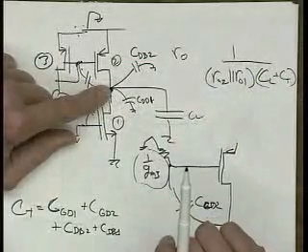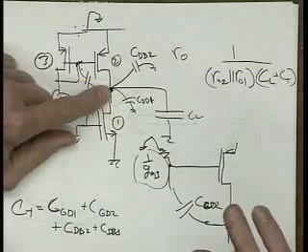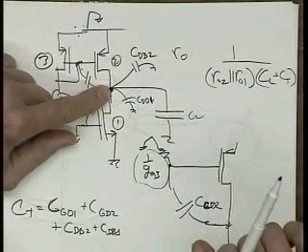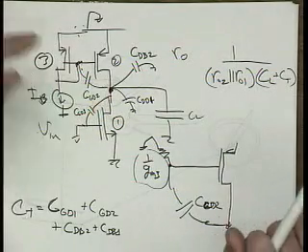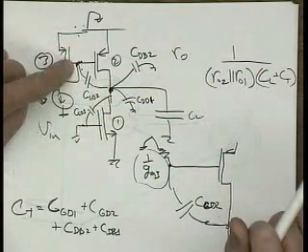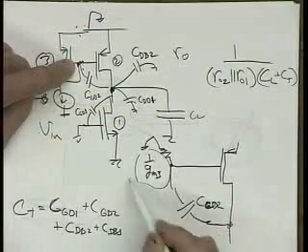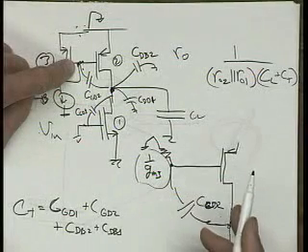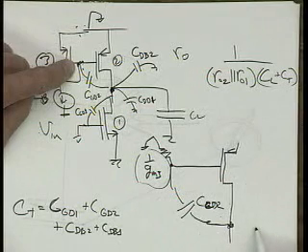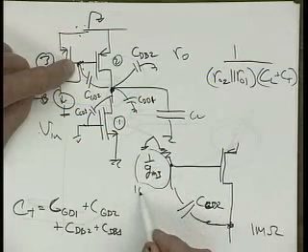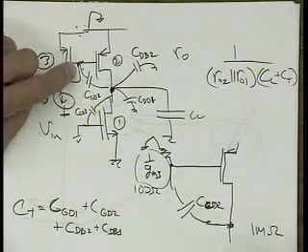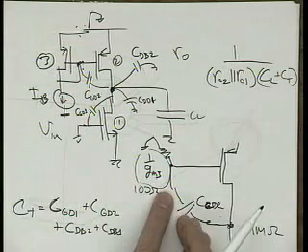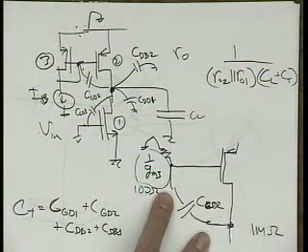Okay, Professor. Yep. Gentleman, question? Okay. So is there CGD2? Do you assume it's a capacitor to ground though? Well, if 1 over GM is small, yeah, you can pretty much assume it's a ground, right? If this node here is megohms, okay, and this is 100 ohms, right? If I figure out the time constant for this capacitor, it's going to be a megohm plus 100 ohms, right? The 100 ohms is negligible, right?